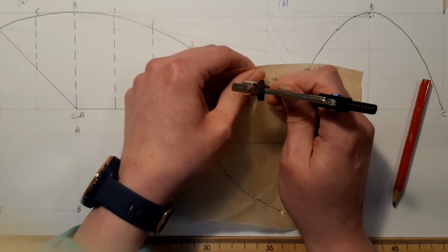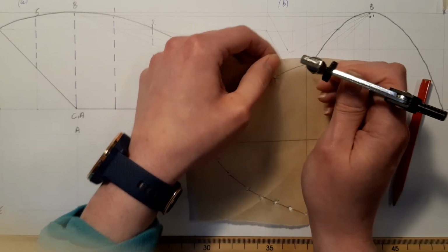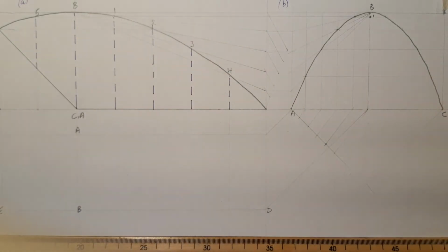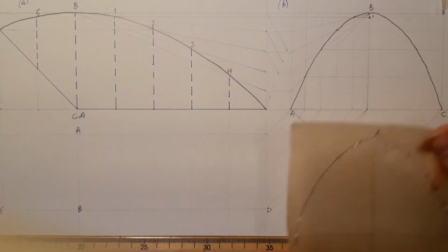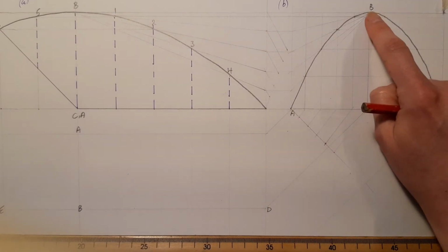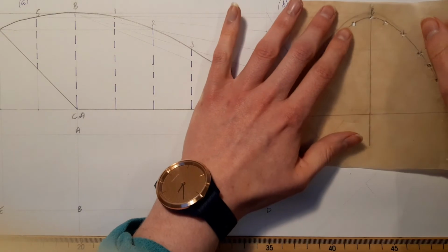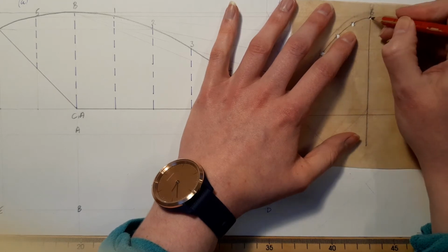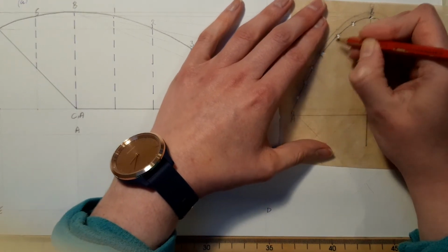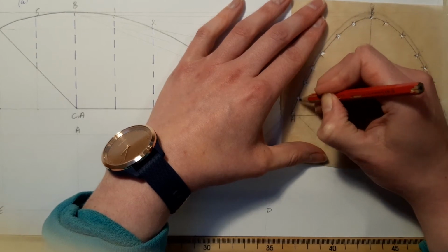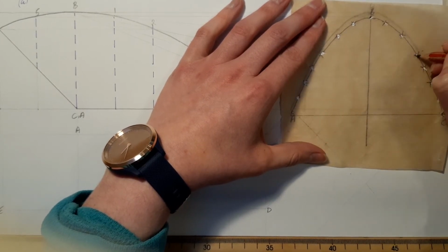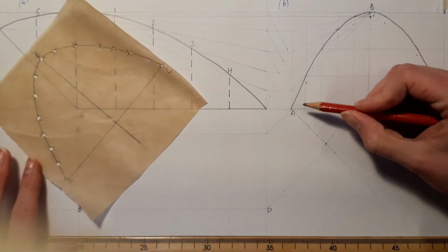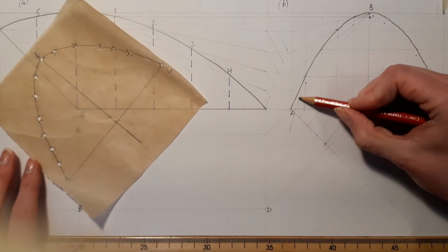Now this is baking paper, but obviously you can use tracing paper as well. It's just a little bit more expensive than the baking paper. Okay, so I have my initial curve. I have my tracing paper with all the holes in it. Now B is now moved down to position 1. So put B on the point 1, make sure your axis is aligned. And with each of the points, all you want to do is poke a little hole through with your pencil for each of them, and we're going to redraw the curve, and the most important points will be the ones on the actual ground. So as you can see, I have all my points, and all I'm going to do is join them together.